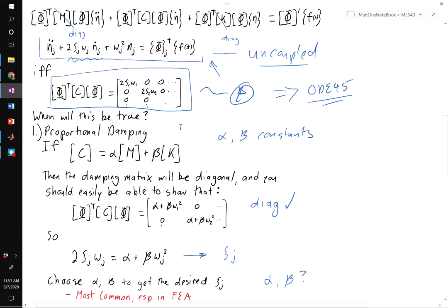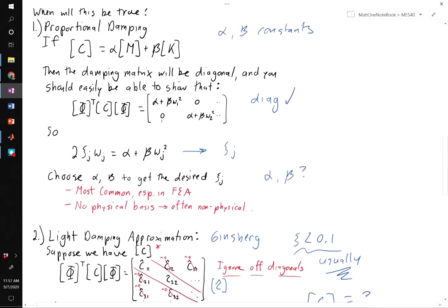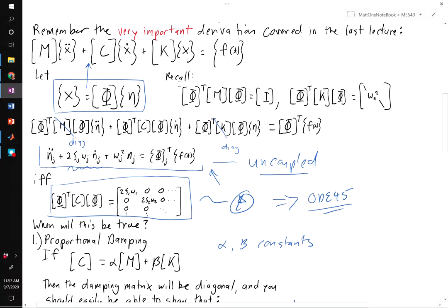And so when we measure mode shapes, we can't tell the structure we've assumed light damping. It just does what it's going to do. And when we try to make sense of the measurements, we might see some evidence of non-proportional damping. And so we'll watch for that. But for the most part, we will make this assumption, and we'll find that this works really well.